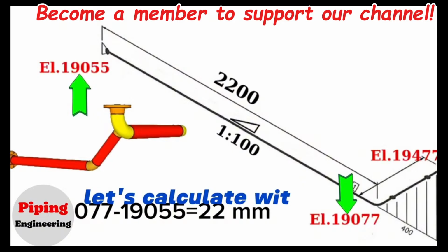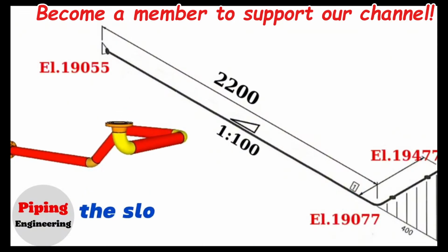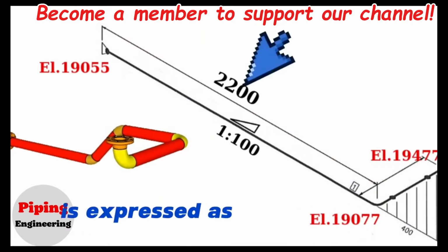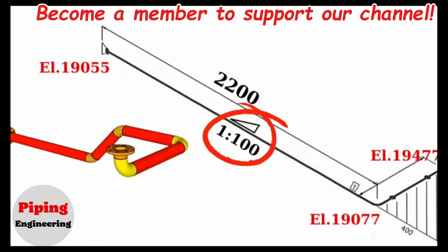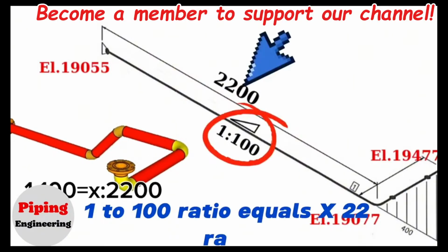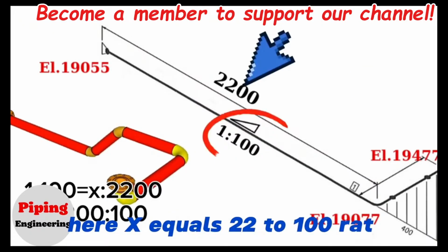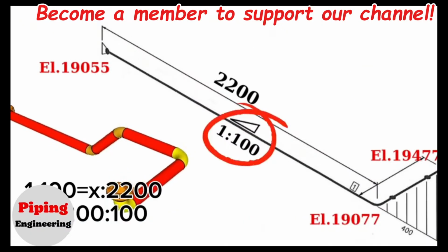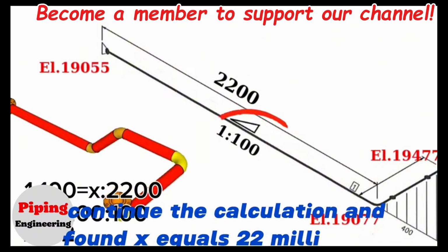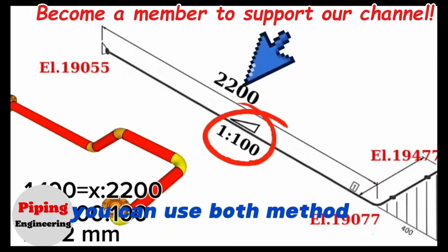Let's calculate with the slope ratio now. In this pipe isometric drawing, the slope at a horizontal distance of 2,200 is expressed as a ratio of 1 to 100. 1 to 100 ratio equals x to 2200 ratio. Here x equals 2200 over 100. Continuing the calculation, we find x equals 22 millimeters. When you want to calculate a slope, you can use both methods on the piping drawing.